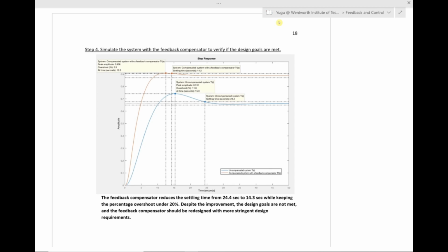As you can see, designing a rate sensor, which is a type of feedback compensator, relies on designing a PD controller. There's an extra step in the end that you have to perform to manipulate the math such that you can translate the PD controller to a rate sensor's transfer function.